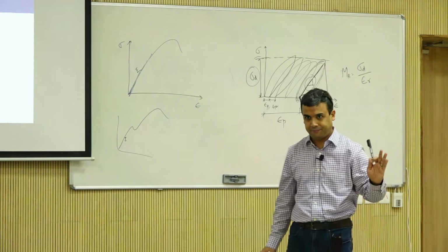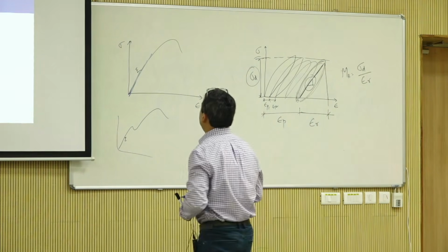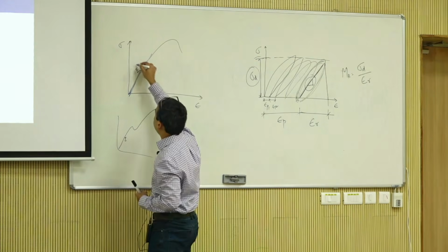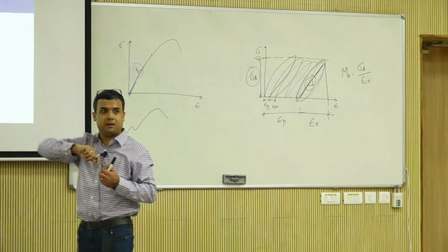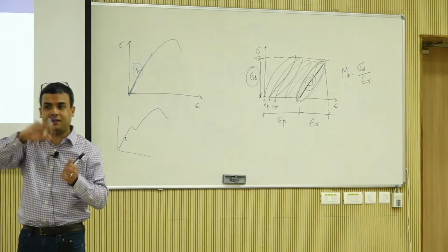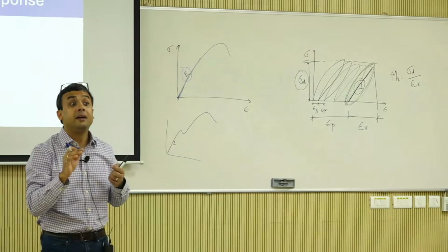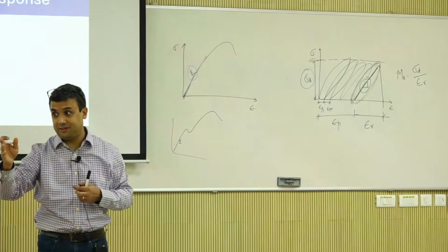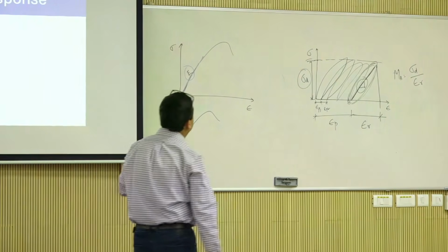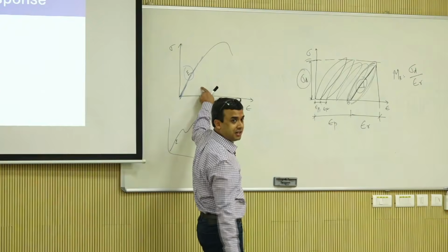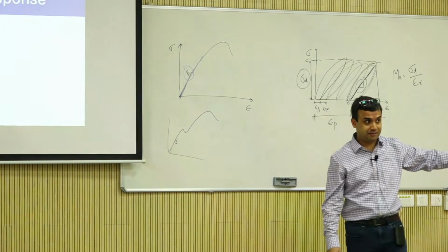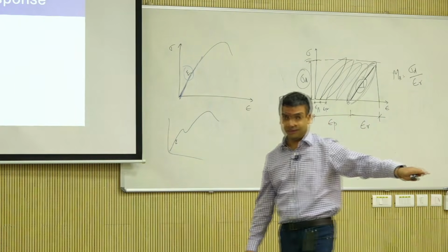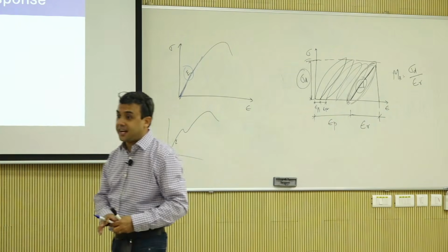Now let's go back to the definition of modulus. What kind of a modulus is it? The hint is mathematics, or graph theory. Tangent modulus. It's a tangential modulus. You're drawing a tangent to the stress strain curve. What are you drawing here? It's a secant modulus, right? So it's a secant modulus.